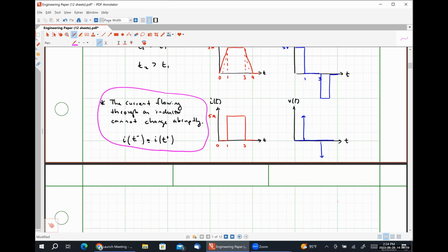An interesting thing here, because this is a little bit of a tangent, but most mechanical switches actually have springs and stuff like that in them to cause them to open very rapidly to help clear that fault inside of the device so that you don't get sparks elsewhere that could be damaging. So switches and stuff are designed specifically to be able to withstand that huge induced voltage that's trying to keep that current flowing for some small amount of time before it can settle to a value. So anyway, all right,